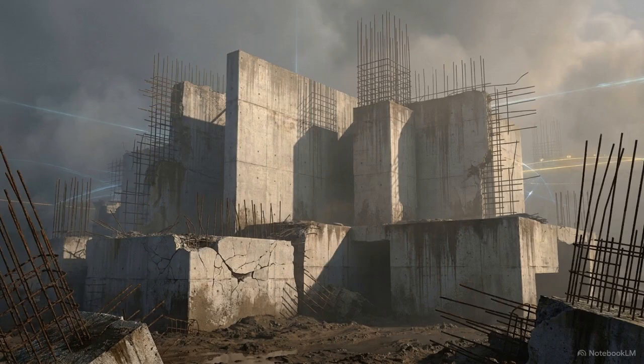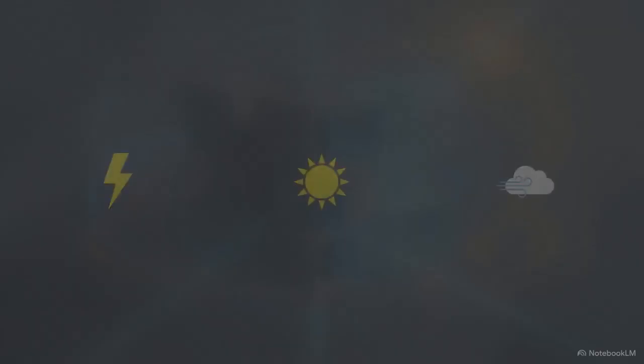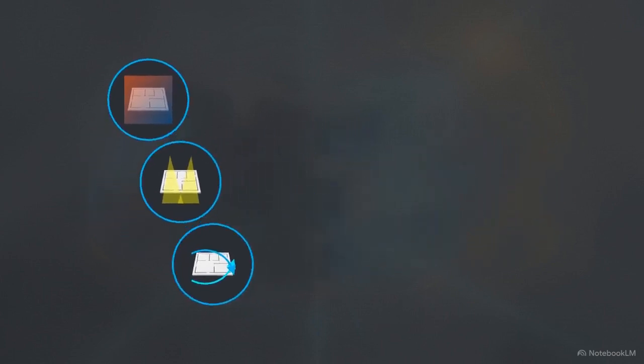Instead of waiting for physical construction to discover an architectural failure, BPS allows us to run highly accurate tests on energy consumption, natural light quality, and wind flow entirely during the design phase. We divide these environmental forces into distinct categories called simulation domains. Each domain isolates a specific physical phenomenon, like thermal heat transfer, natural daylight penetration, or the fluid movement of air.